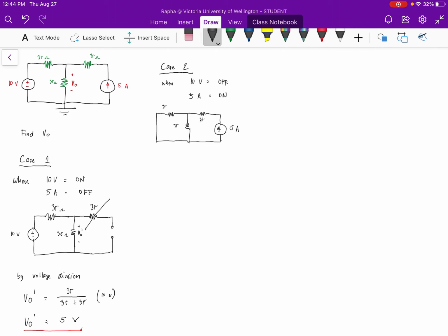In order to solve for the current that flows to the middle resistor branch, we need to simplify the parallel resistor network first. This one. So Req, the resulting equivalent resistance, is equal to the parallel sum of these two resistors, 35 times 35 over 35 plus 35.